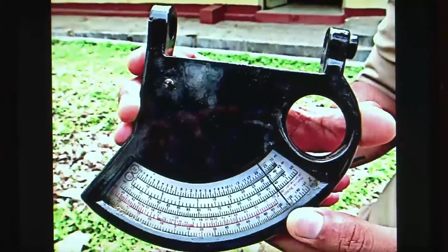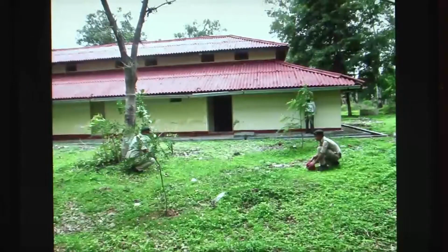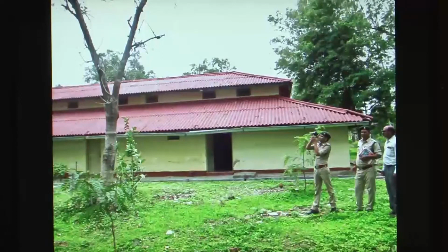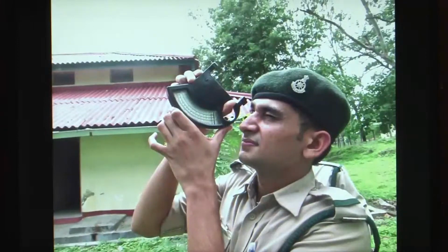Here we had the instrument. To measure the height, you would first measure the distance from the base of the tree, which you can do with a tape or with a range finder or maybe with your steps. Then you would stand to one side and arrange your instrument such that your eye, the circular hole that is your optical hole, the crosshairs in the front and the top of the tree come in the same line. Then you would press this button. When you press this button, the pointer becomes fixed and then you can take the readings from the scale. But this instrument also does something very smart.